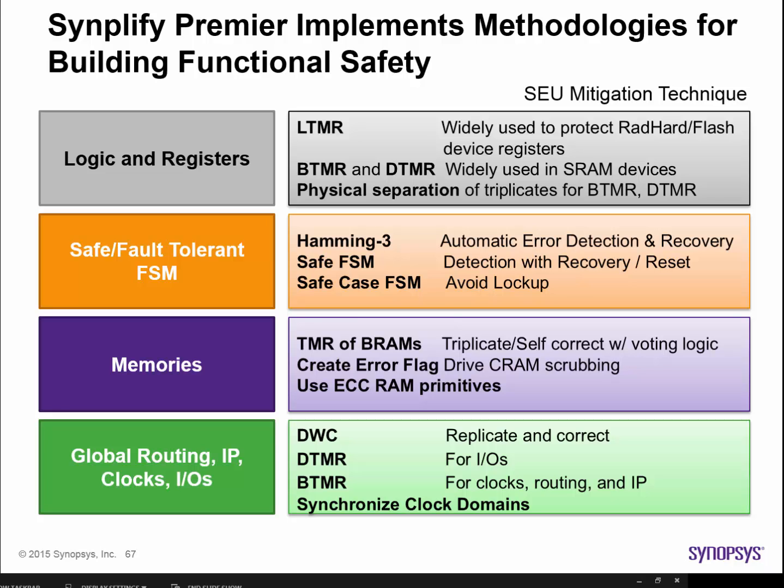The choice of which primitive is in the most need of protection will depend upon the FPGA device type, SRAM, or flash antifuse. All devices benefit from one or more of these techniques. Please refer to the introductory video, How and Where to Design in Functional Safety. This will give you more details. The good news is that all of these techniques are automated by and available in the Synplify Premier software.